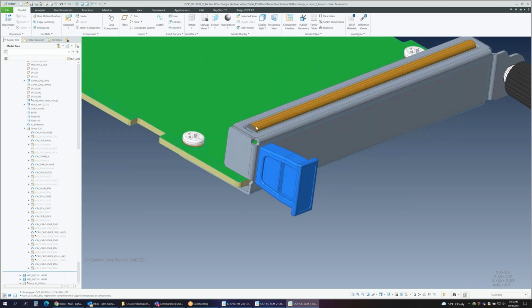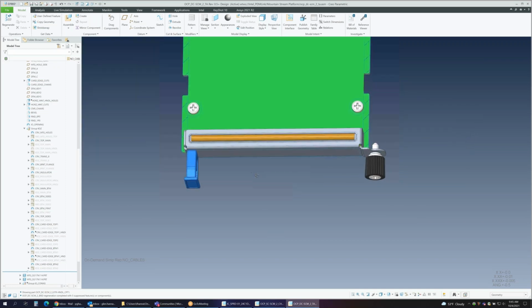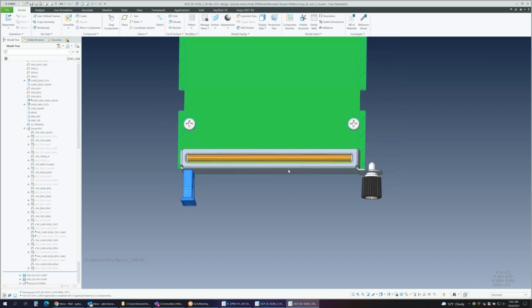One of the things we're considering is the ability to have not only the EMI fingers you're used to seeing on some brackets, but also a gasket type material. If we could use the same gasket profile on the sides and tops, that would be ideal. So we're looking to enable both EMI fingers for EMI suppression as well as fabric over foam gaskets.